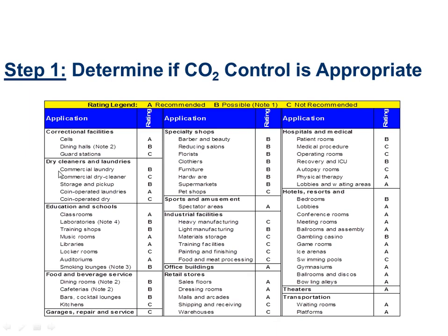they have some kind of chemical process. So at a prison, a guard station is a bad case because hopefully the guard station is always fully manned, not half manned. So there's no reason to reduce the outside air because everybody should show up for work. If you got dry cleaners, it's a bad idea because the ventilation is being dictated by the chemicals, not by the 3 guys that work there.